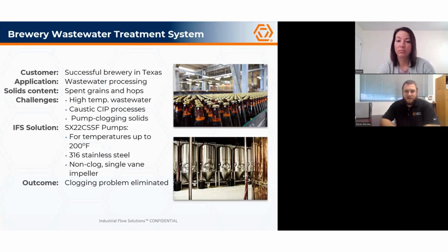The SX22 CSSF was the ideal choice as it utilized a non-clog impeller design to pass the small solids present in brewery wastewater. The pump is also constructed of precision cast 316 stainless steel, which can resist the corrosive effects of the wort and the various chemicals present in the clean in place process.